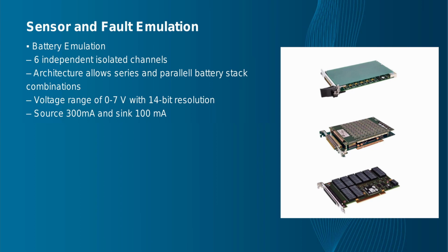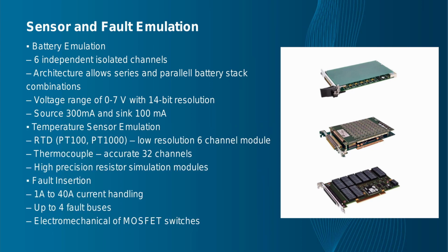In addition to battery voltage emulation, we need temperature sensor simulation cards and fault insertion cards to complete the BMS hardware-in-the-loop setup. Speedgoat provides various options for temperature sensor emulator cards and fault insertion.